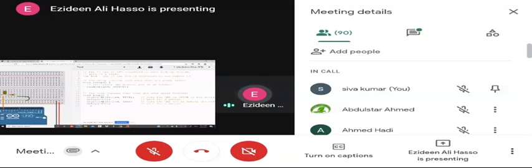It's a microcontroller, yeah. In this line I'm saying digitalWrite, which is also a keyword. I write to the LED, which is pin number 13, HIGH, which is 5 volts. Then I insert a delay of 2000 milliseconds, which means 2 seconds.